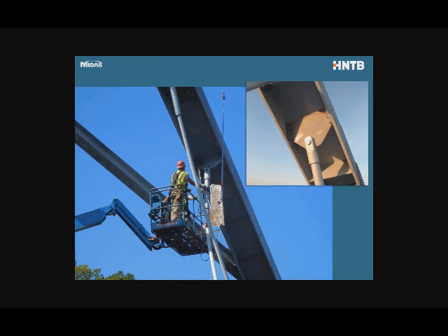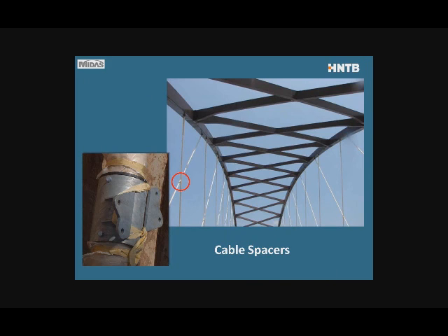With the strand-by-strand system that I've shown earlier, the multi-strand system, you can actually replace 1 strand at a time. So pretty much if you have large arch rib and large cables, you want to go with probably the multi-strand system, and if you have smaller structures, you're better off with this pin-type connection.